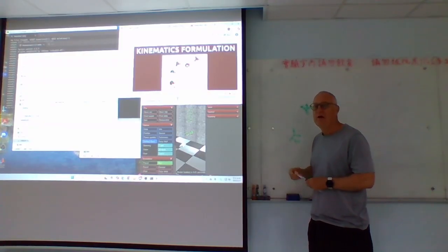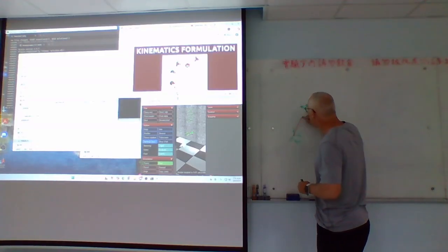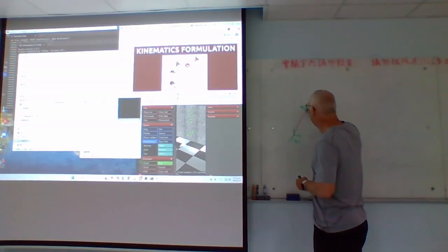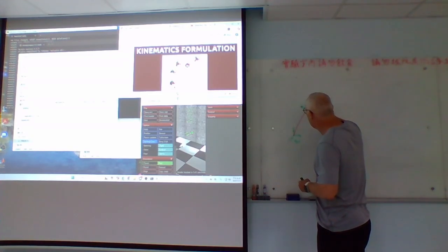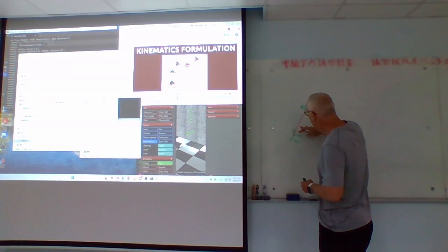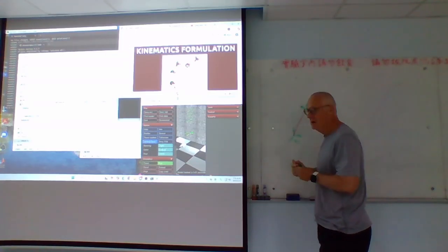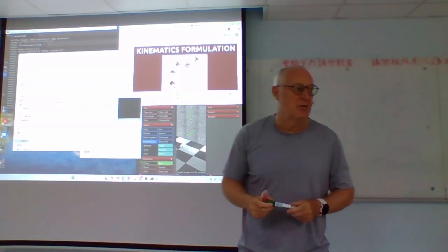So then that I can break down into a translation, right? And the rotation that says, from here to there, I would have to rotate around the x-axis this much, so this would be theta here maybe, and we also rotate around x this way, and then I rotate around x another 90 degrees to bring the z-axis up and the y-axis backwards, if that's the transformation we have.